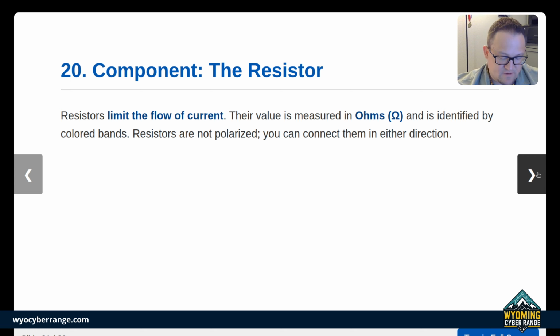I get the same question every year: how do I know what hardware takes what voltage? There really is only one answer. Go look at the manufacturer's spec. The manufacturer will provide you with a spec saying normal operating temperatures or normal operating voltage ranges. They'll tell you everything you need to know. I do say a range because most of these devices can operate within a range, maybe 1.1 volt to 1.3 volt. They're not always hard-coded, as in you need 5 volts on the dot or this is going to break. Normally there's a range.